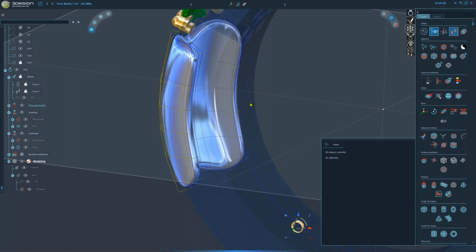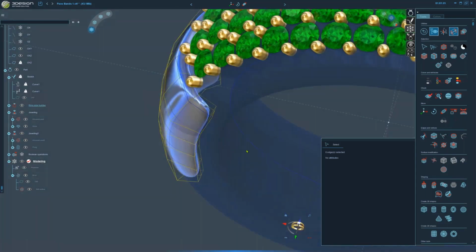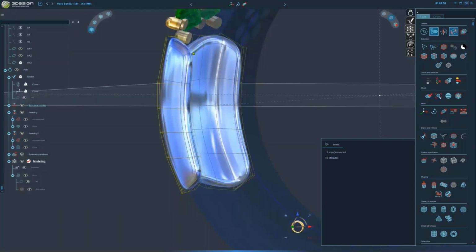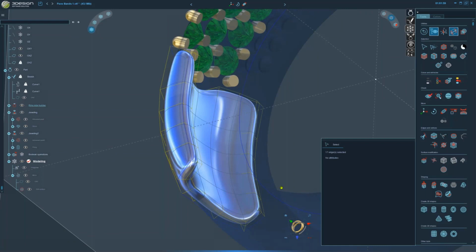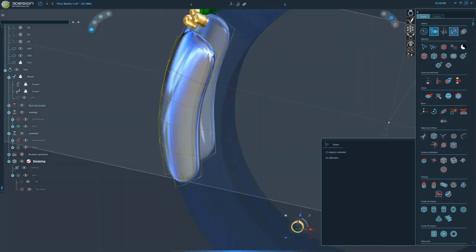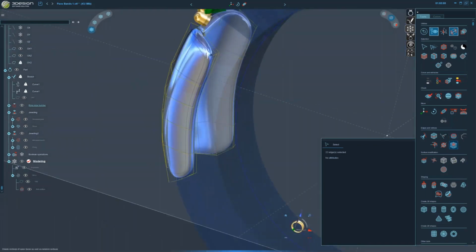So just like I would on a NURBS curve, we can put 3 points closer together. In that case, what we're doing is filleting. So I'm going to take this edge and double click it. And I'm going to select this edge with control and double click it. And the same thing with this edge and the one back here. So I want that whole edge selected each side. And we're going to add a fillet. Okay, so fillet or chamfer, we can call it chamfer here, same idea.